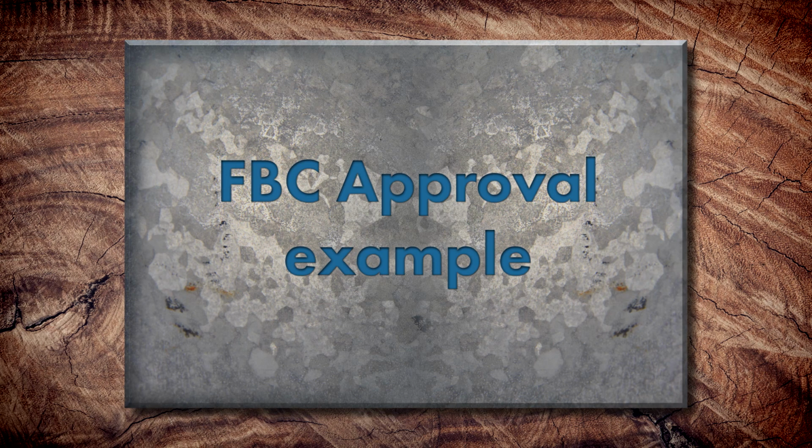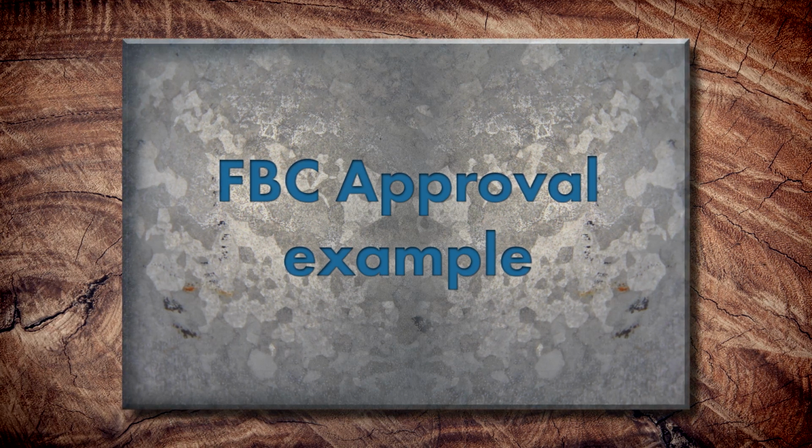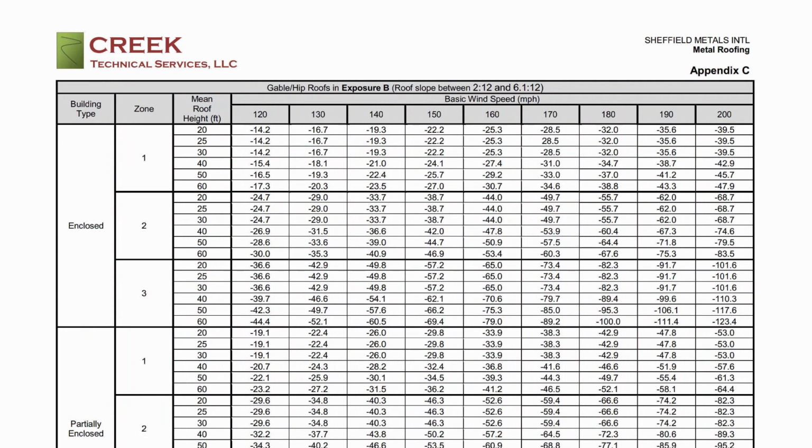All right, so what are we looking at here? Okay, so this is the chart on our FPC approval, Florida product approval. It was done by a third-party professional engineer. And this gives us an idea of how our design pressures can correlate into wind speeds when we're looking at different projects, before you go out and, again, spend money on a third-party engineer to do project-specific calculations.